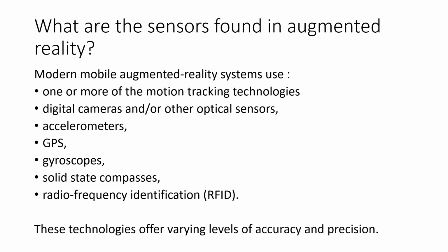You also need a GPS. GPS is for the positioning of the person in the world. Now, if you are in an indoor environment, the GPS signal may not be available. What you can do then is take your last known GPS location and feed it to your software. Gyroscopes give you the tilts, so all the XYZ tilts can be measured using gyroscopes.